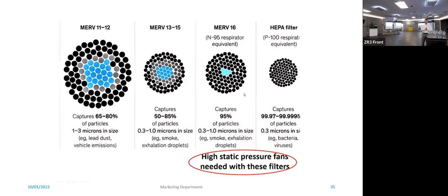It's known as the MPPS, most penetrating particle size, and that's the point at which diffusion and impaction meet. That's just the particle that's going to find its way through that HEPA filter first. Much like molecules do the same thing. We look at vapor pressure, molecular weight of the molecule, kinetic energy if we're adding a heat load, and we understand which molecule is going to possibly break through the carbon filter first.